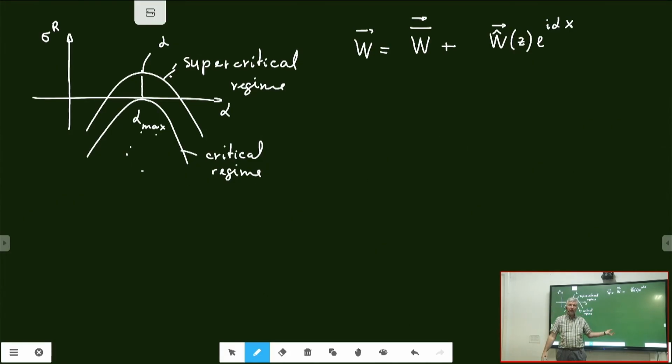Remember, during the break I discussed that we have this wave pattern, which we impose and add on top of the base flow, but we don't know what we're actually adding, how strong it is. I chose the coefficient which multiplies the eigenfunction just arbitrarily. I said, well, let's make it 0.1. Why 0.1? Why not 0.2? Well, because it looks good, right?